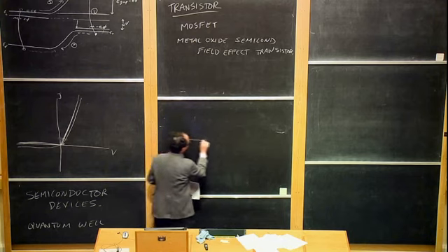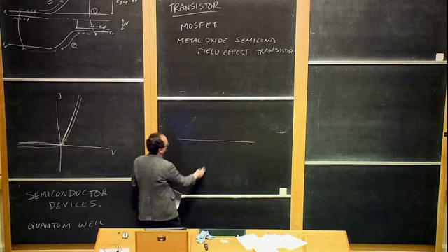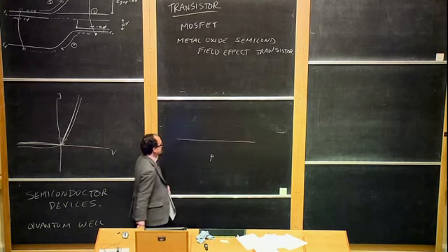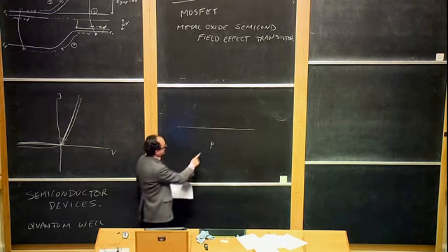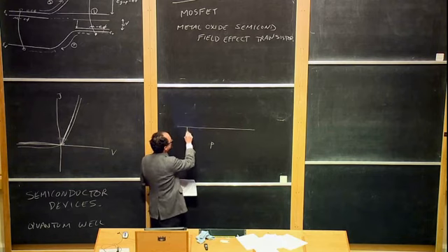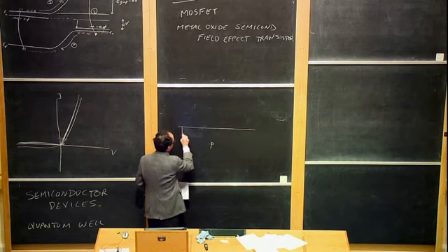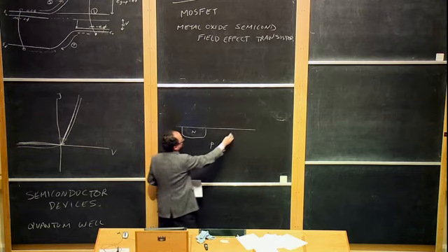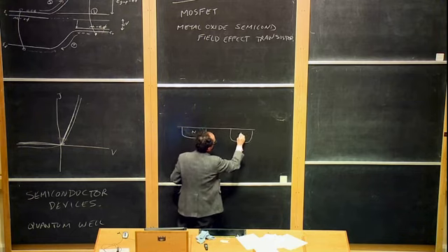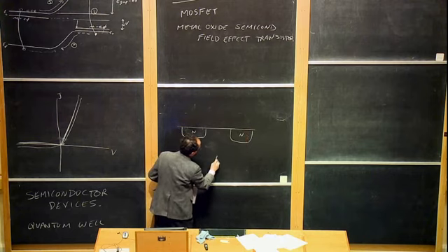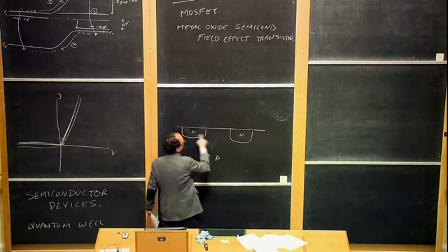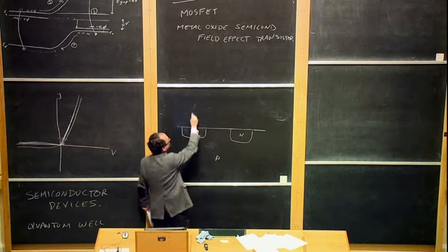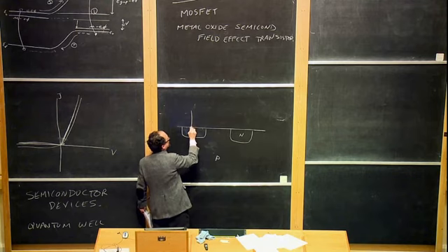You take a big piece of semiconductor and you p-dope it, and it has a surface like this. You could do it backwards. You could n-dope it if you wanted to, but let's imagine it's p-doped. And then we take 2 small regions, and we n-dope them. Let's make it a little bigger. This region here, n-dope, and then we'll n-dope this region here. And this is all p-doped. Okay, so what we have now is a surface with an n-dope, n-dope, and a big bulk with p-doped.